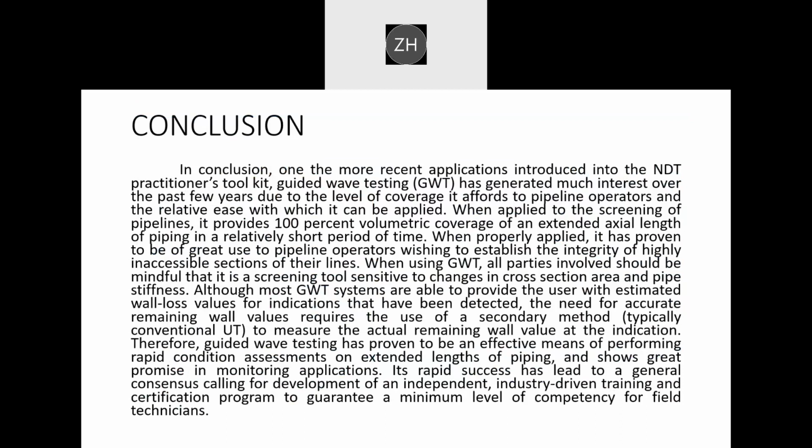To sum up, one of the more recent applications introduced into the NDT practitioner's toolkit, which is Guided Wave Testing, GWT, has generated much interest over the past few years due to the level of coverage it affords to pipeline operators and the relative ease with which it can be applied. When applied to the screening of pipelines, it provides 100% volumetric coverage of an extended axial length of piping in a relatively short period of time.